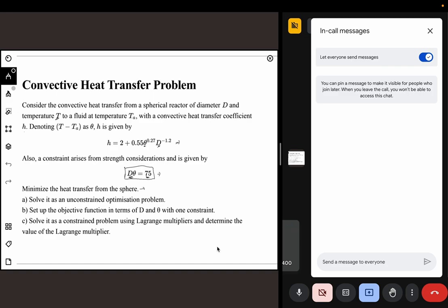For example, if you are solving some fluid dynamics problem or heat transfer problem, these are usually the... For example, if you want to design a car or something, there will be some standards that will tell you, okay, this should be the minimum height that you have to meet. If you are designing an air conditioning system or some ducting system, you know that there is a certain amount of noise level that you have to maintain. There are some standards that say you need to have this much access space in case of maintenance or something. So your duct diameter cannot be smaller than this. There will also be a constraint which says the flow rate inside the duct cannot be greater than this, because that will cause more noise or something. All those things have to be put in.